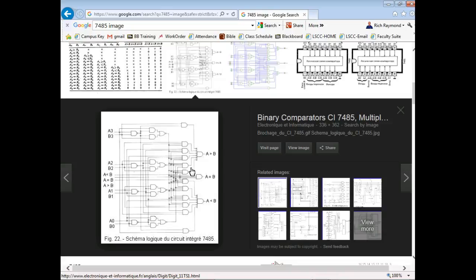The split wrap tool is a little easier because you don't have to strip the wire. It's got a little blade on the inside, and it strips off the insulation against the post for you. It's real fast. And what's nice about this is that if you make a printed circuit board, then it's fixed, right? But with this, if you change things around, you just unscrew it, come back in the opposite direction, pull it off, and you can rewire it or do whatever you want. This is wire wrap. So that's what I put in that machine that I made.